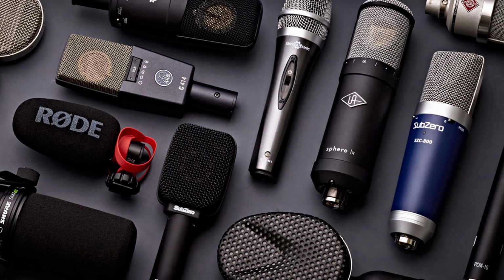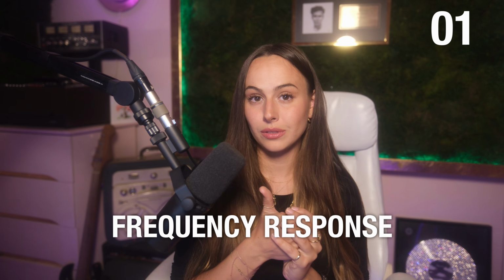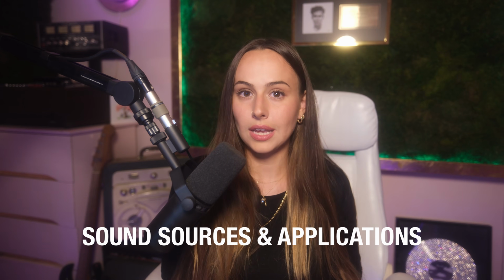So when you're choosing what microphone will be best for you, there are certain specifications that you need to consider. So number 1 is frequency response. This defines the range of frequencies that the microphone can accurately reproduce, as well as any sort of coloration that it gives. Dynamic microphones typically have a frequency range of about 50 Hz to about 15 kHz. So this is very helpful for a lot of different sound sources and applications. However, thing to note, 15 kilohertz or 16 kilohertz is gonna darken your sound a little bit. You're not gonna get those super sparkly high ends at all.